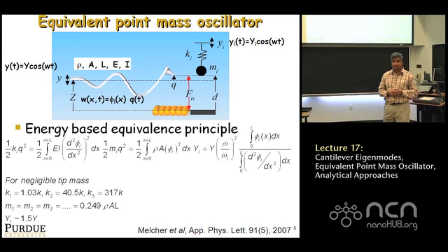So what it means effectively is when you've got a beam, you've got many eigenmodes, right? As we discussed, at different frequencies. When you choose to drive it at one particular peak, you effectively have an oscillator with a certain spring constant and a certain Q factor.